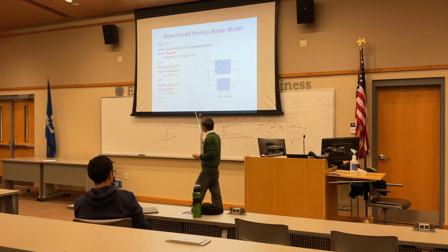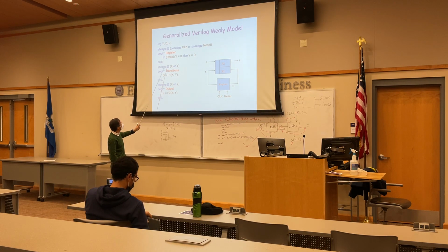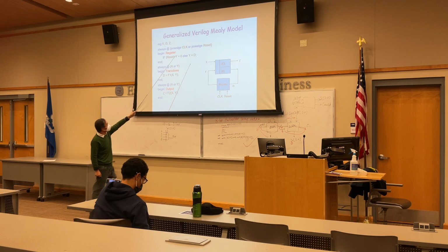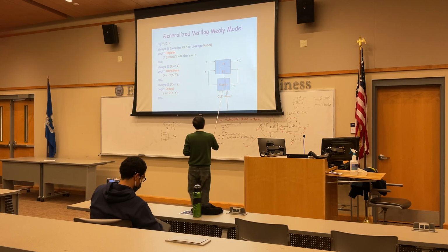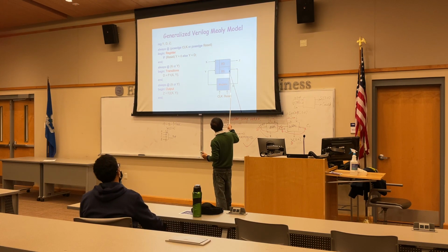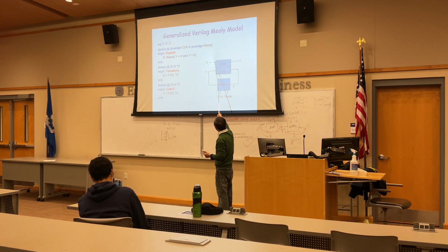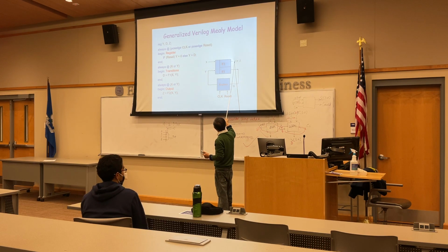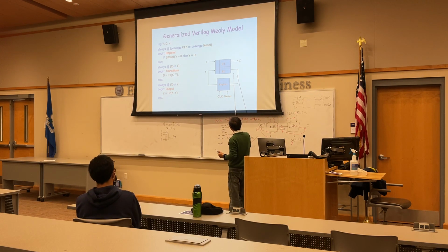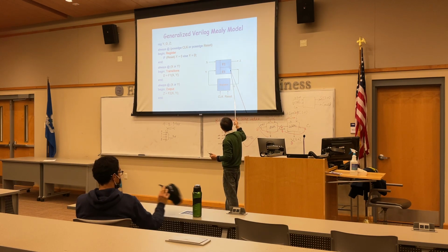In sequential circuit design, we are going to mainly have these 3 modules. This is an example Mealy machine module. This is the current state, and this one is the next state. This is the input and output. The output depends on both input and current state and goes to F2. And this F1, using the current state and the input, decides the next state.